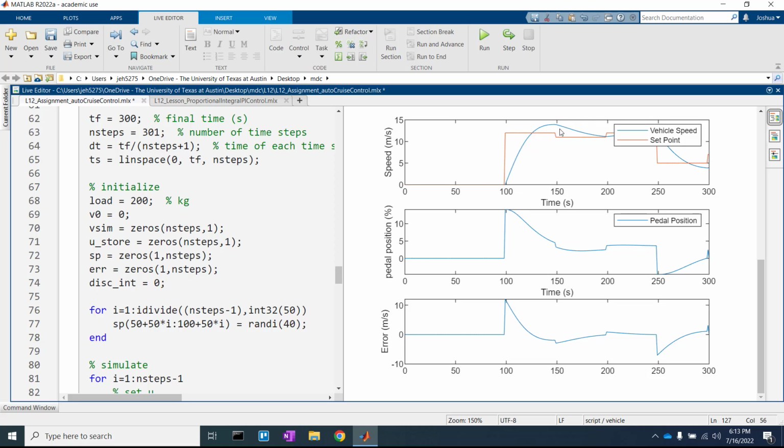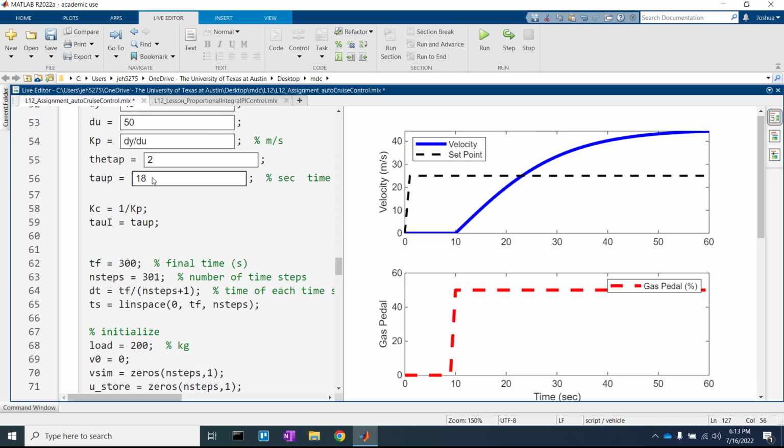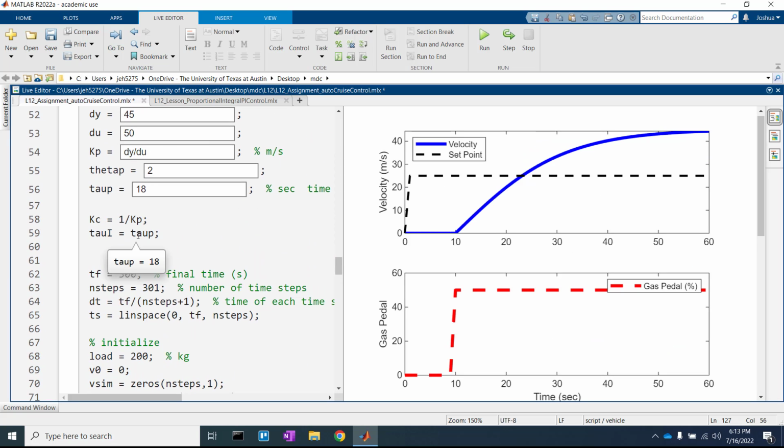The overshoot is generally caused by one of two things. It's either caused by the integral of absolute error, so we have this integral of error underneath, and we need to overshoot it until we get right back down. Basically, we need to match the area underneath and up top until they are equal. That is one problem that happens sometimes. And so what we can do is make our integral control a little bit more conservative.